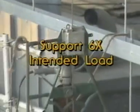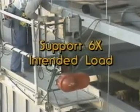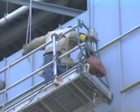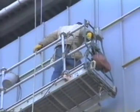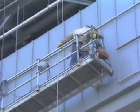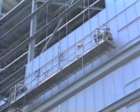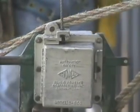The wires or synthetic or fiber ropes used to support a suspended scaffold must be rated capable of supporting at least 6 times the maximum intended load. This includes the weight of the scaffold itself, as well as that of the workers, tools, and materials on board. Most suspended scaffolds are raised and lowered by a mechanical hoist. The hoist should be checked regularly to make certain it is operating safely and has a secondary emergency brake that is in good working order.